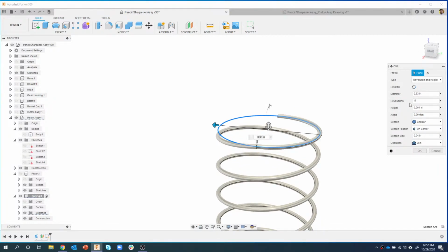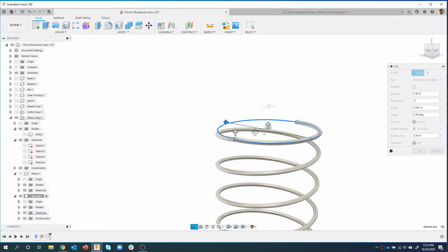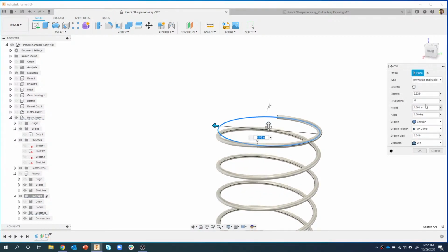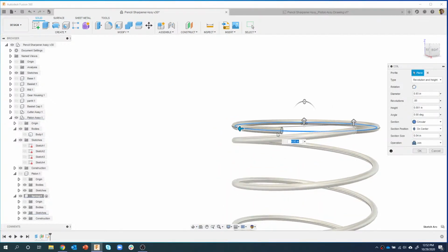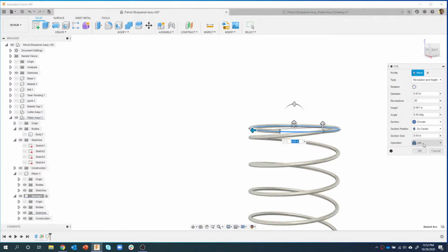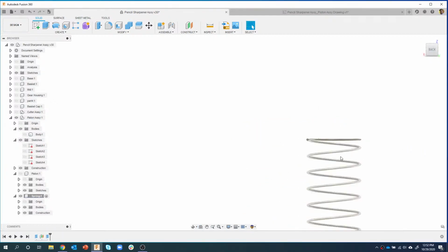Let's type in 0.5, and there you can see what it's going to do. Okay, so I found that 0.85, I think, is a good distance in this case. It goes mostly all the way around before it starts to intersect. I'm going to join those together, and now you can kind of see these springs.